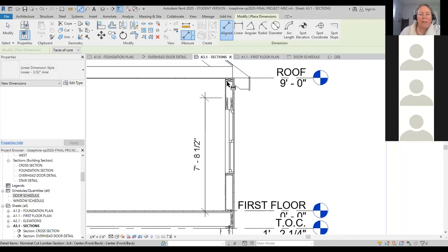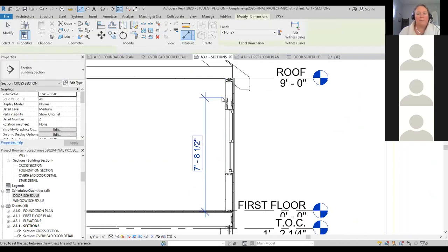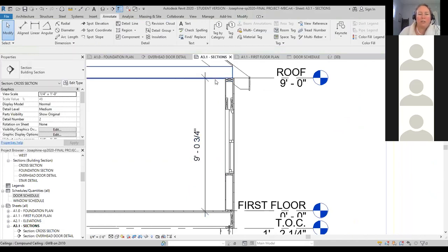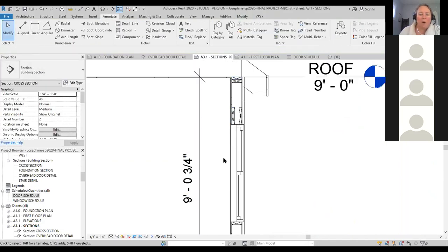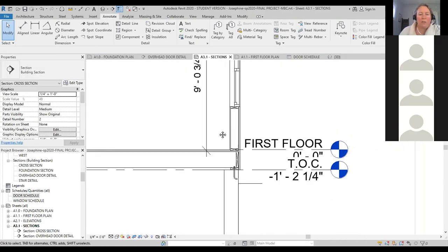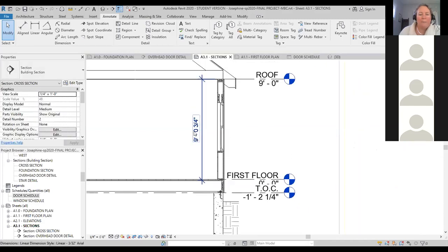And then if I add the 3 inches to that, I'm going to get, let's move that all the way up to here. I have 9 feet 3/4 inches as a top of wall to rough floor, subfloor dimension. If I take that number and subtract the actual wall height this needs to be, and this wall height needs to be 6 feet 10 1/2 inches plus 11 1/4 plus 3 inches. If I take that number, that ends up being 7 feet 10 3/4 inches, then I should end up with